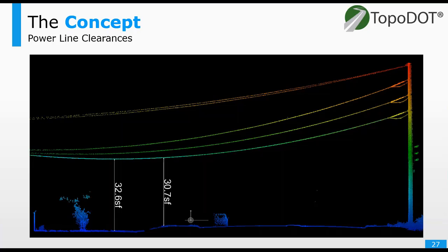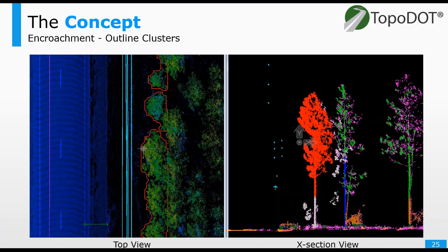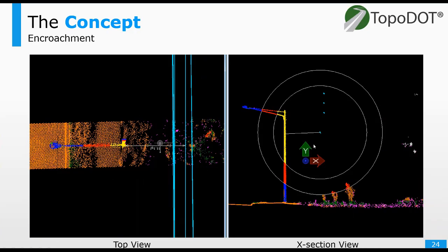All right. Do the encroachment outputs retain minimal distance measurement information? So we have another tool that Mike didn't show, that shows actual clearance dimensions to the encroachment. So you can see the shortest distance between the encroachment and the closest point to the wire. This is another companion tool.